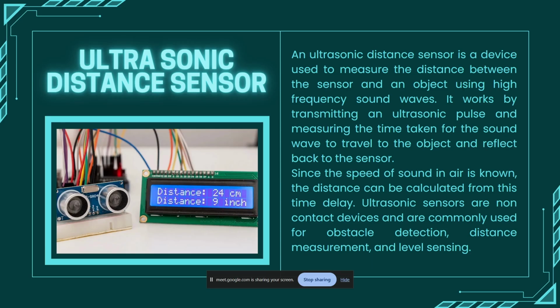It's been a long time since I've had this sensor, and I've been working with it, but I still don't know why there are two meshes or why it looks so weird. Basically, the sound wave goes and is received back, and your sensor is able to figure that out. You measure the time difference between your pulse being generated and it being captured, multiply that time with the velocity of sound, and then divide it by two.